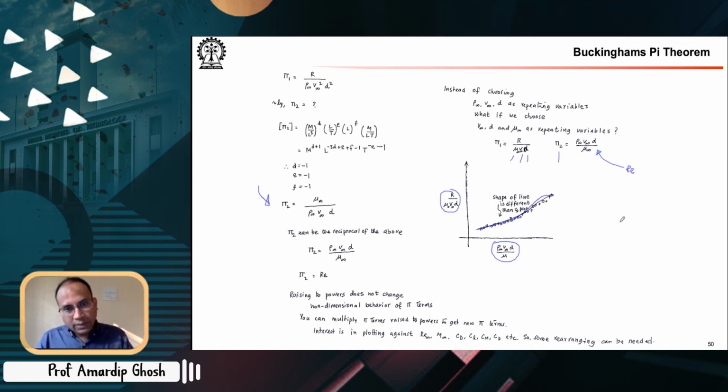On the other hand, with Buckingham's Pi theorem approach, you can figure out the non-dimensional groups, and when you plot them, there is this advantage that since the data has a beautiful collapse on these lines that define the functional relationship between the pi groups, you have a great advantage in interpolating and extrapolating data required for configurations that do not fall exactly on the things with which you have tested.